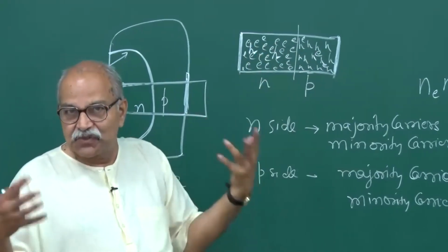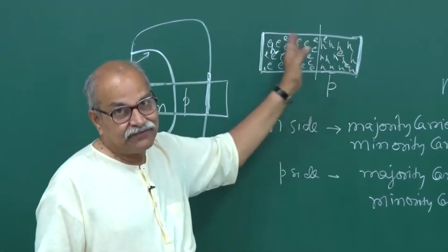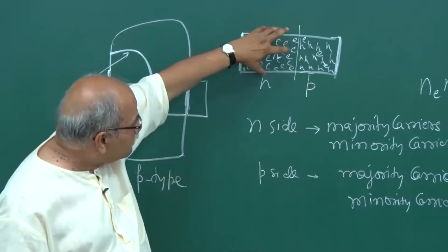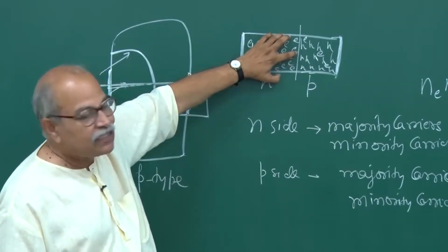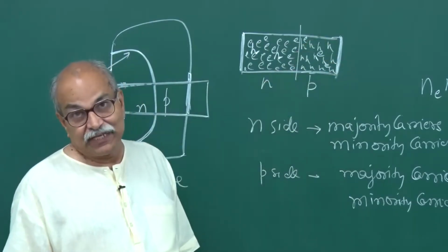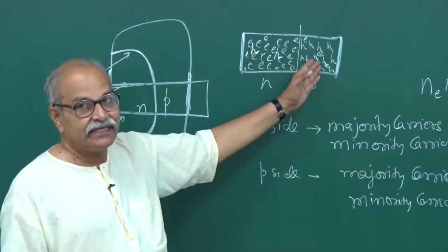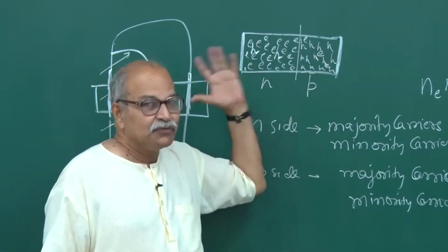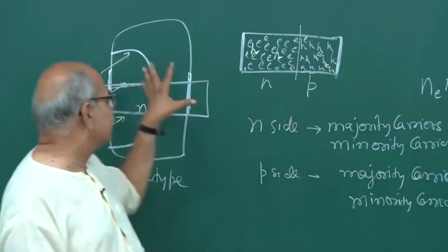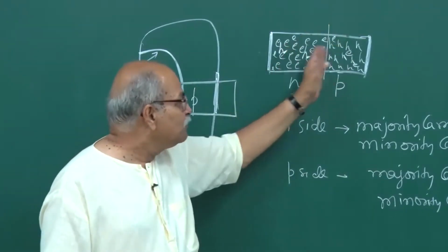So all that usual electron movement and hole movements is allowed in this entire wafer, in this entire material. Therefore, having a large concentration of electrons here and a very small concentration of electrons here is a very non-equilibrium situation. If you have such a huge concentration gradient, and if the movement is allowed, they are allowed to go from here to here. Remember, the whole thing is one single crystal on which you have done all these diffusions, and therefore that movement is allowed.